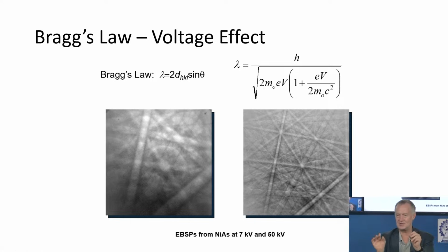We can do relative D-spacings, but to measure exact, like if we're trying to measure strain based on that D-spacing, 0.2% strain, 0.2% is the standard definition for yield strains. We can't measure 0.2% difference, not a prayer. Because we have maybe 1,000 pixels in our image, a band will have maybe 50 pixels across. So if it's 1 pixel difference, that's already 2%. So if we can measure to within 1 pixel, that's 2% strain. But if we use machine learning, maybe we'll see how that comes out.